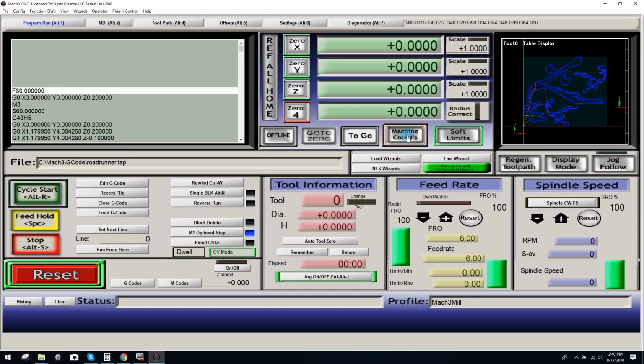First, we want to validate one more time. Get you guys in the habit. You don't have to do it, but I like to be in the habit. I'm anal retentive when it comes to this because I care about my equipment. I will always validate my machine coordinate position so I know where my end stop is, and we also validate once again and know we're in G54. You can see that right here, and we also see we're zeroed all the way across the board. So now we're ready to set our first offset.